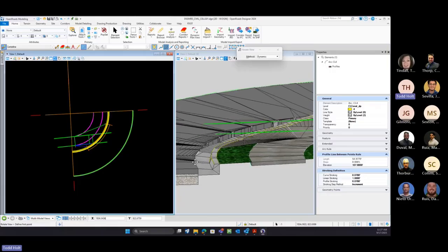So it's tying in nice here, but when we get into that, we have that edge of pavement. So maybe we have the edge of pavement line that we want to put that curb on, and then use a point control or parametric constraint to tie that down, so that the linear template we probably have to look at and reestablish how we want that to rule.